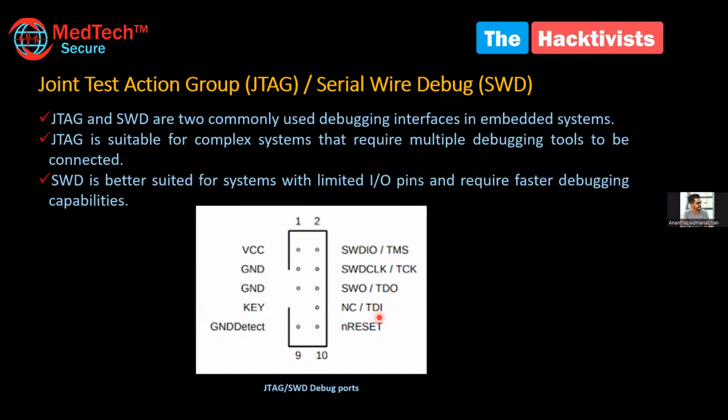But for debugging, it might not be possible, especially for a high-end device, to handle that data through a single pinout. So the JTAG protocol has TDI and TDO separate, input separately and output separately, and TCK is the clock. Everything will have a clock and a ground. From the hardware perspective, if we want to test something, we need to find the voltage, ground, and clock. Voltage is mentioned as VCC, and ground is GND. We'll look at that in a later slide.